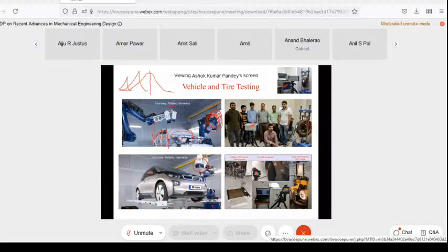You can define the region, because with the help of laser, you can't really do measurement over a black portion, because the reflectivity is quite less. So in that particular case, you define the region. You can do some spray, and then the laser will come and scan over all the surfaces, and meanwhile you can put the shaker here, and it will excite it.